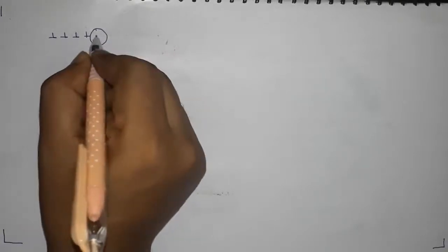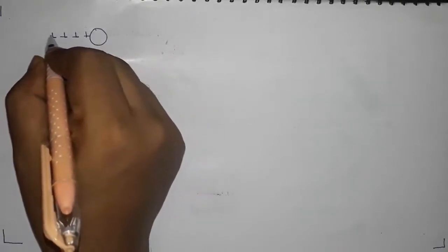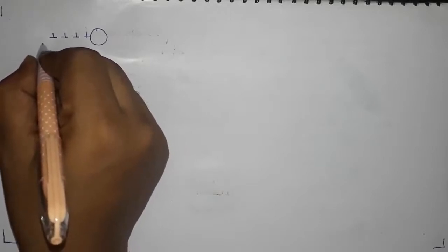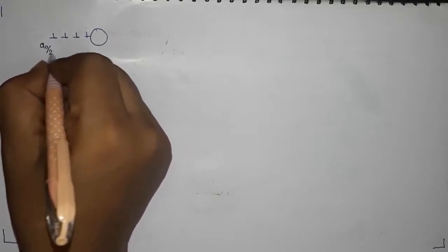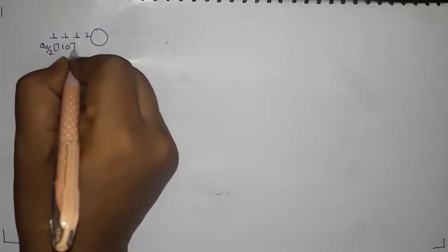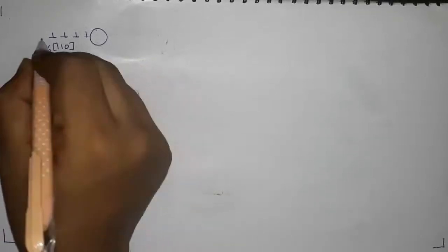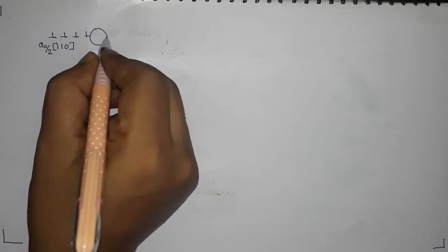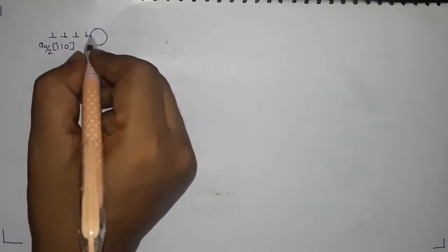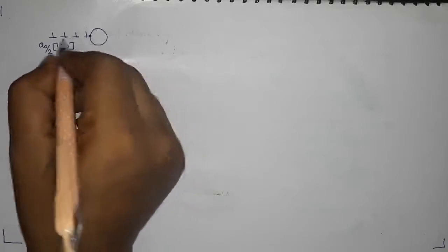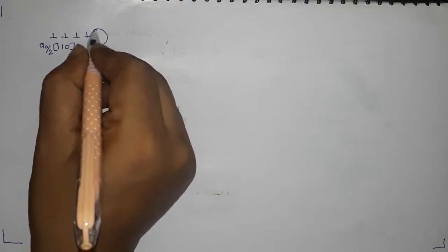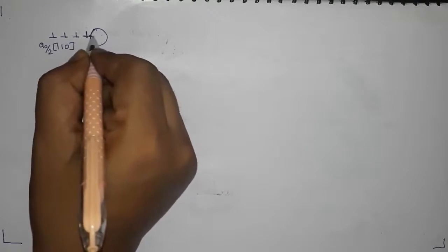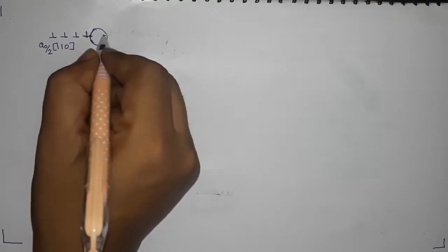Okay, and so this is an edge dislocation. Let us assume that this is an edge dislocation in FCC, so I will have an a0/2 <110> kind of dislocation which is moving in the <110> direction, right? And they keep on piling up at this interface because there is a precipitate. That means the <110> direction does not exist after this point.